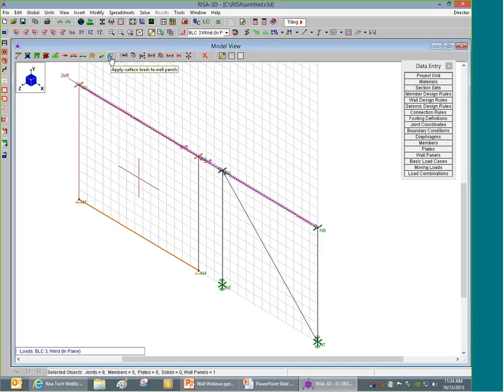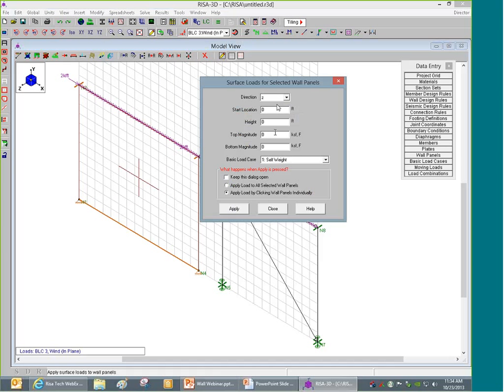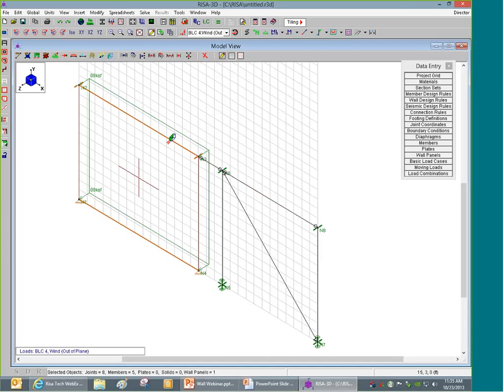And then for out-of-plane wind, let's say that maybe the wind is just going to blow right through this steel frame. We're not concerned about that. But for the wall, we'll assume that we're in a hurricane zone. Maybe we're down in Miami where we're just going to get some extreme out-of-plane wind loads, maybe 80 pounds a square foot. I'm going to come in and apply that to the wall as an out-of-plane surface load.